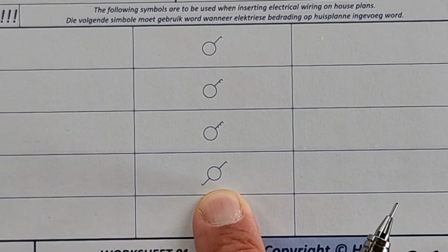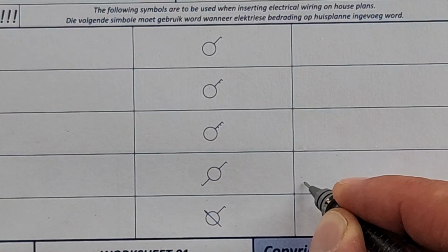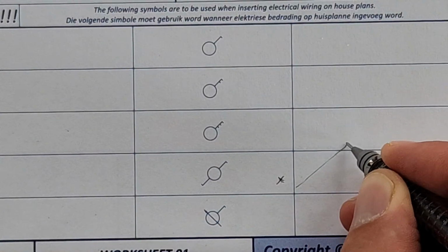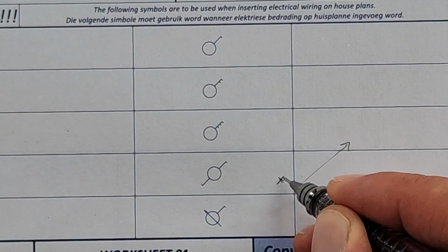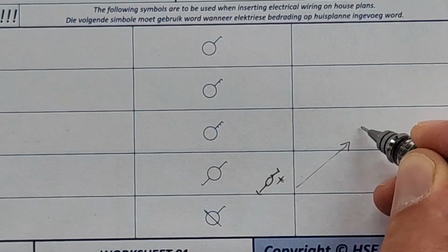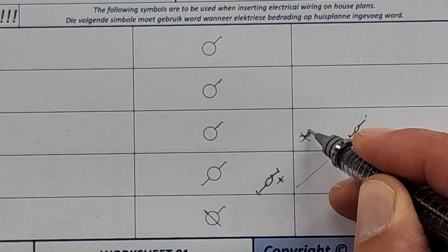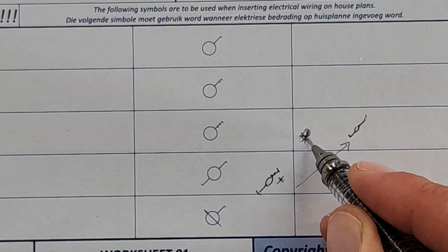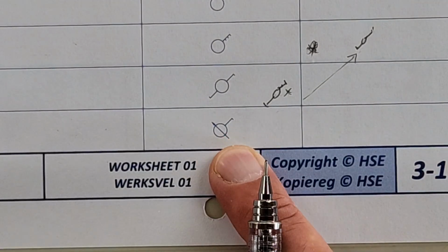And then this one is a two-way switch, twee-rigting skakelaar. That's if I come in at steps, I switch on the light at the bottom, then I go up the steps to the next floor. Oh shucks, now I have to come down to switch off that same light. No, if I have a two-way switch here and one on the top of the steps, then I can switch on the light here, go up the steps, switch that same light off. Two-way switch. And then the last one is a dimmer